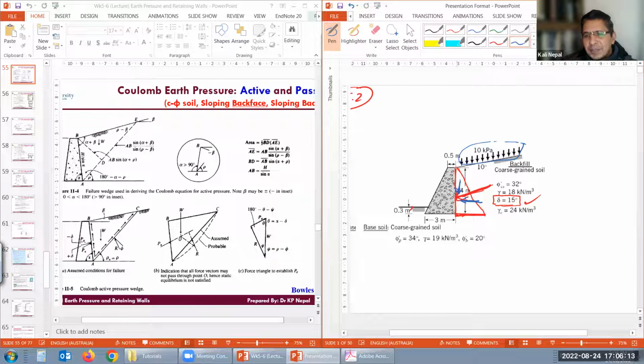Surcharge gives what? Can I just draw outside of that so that I know what I'm doing? So it would give a constant pressure throughout. Good, right? So that's what we need to find now, and divide into two parts. For this, it also acts at the same angle, right? That was the angle there, 15 degrees. So that's a 15-degree angle, and convert into vertical and horizontal.